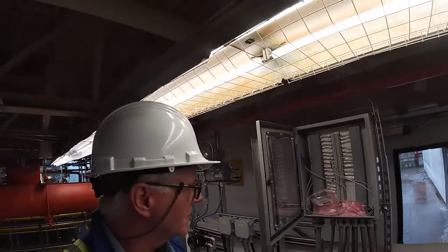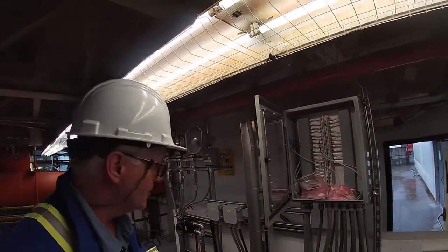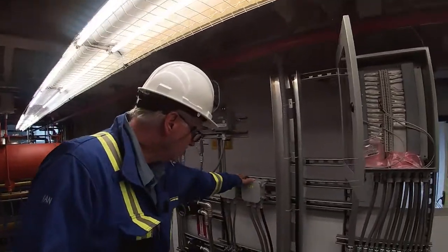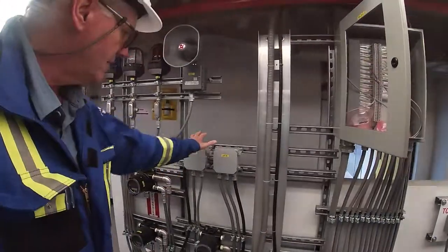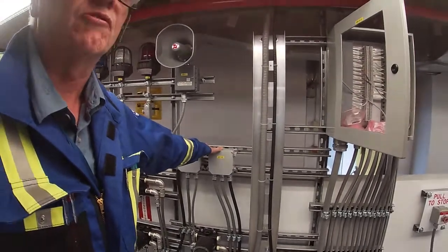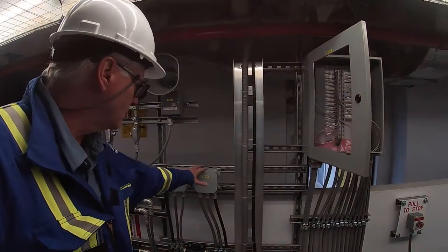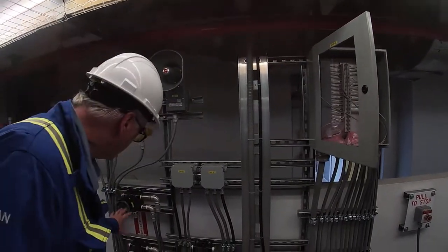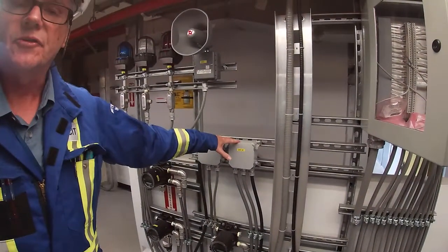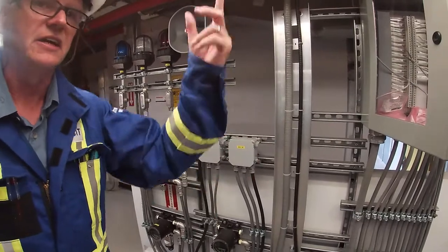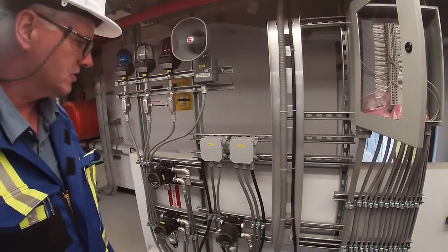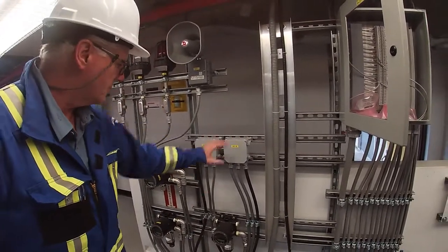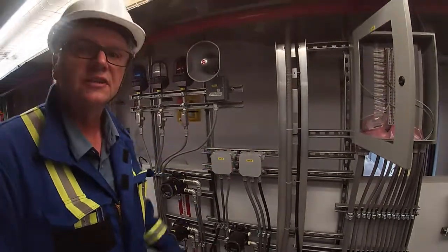It's the same thing. One last thing is these devices require a separate 24-volt power supply. So we mounted a couple of power supplies here. That's where these 3 devices are getting their power from, and we tied it in on a circuit with another power supply. So these are the 24 volts in here, and we take our 110 in here to these power supplies.